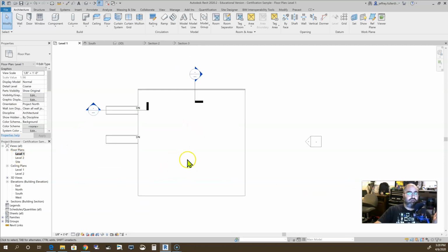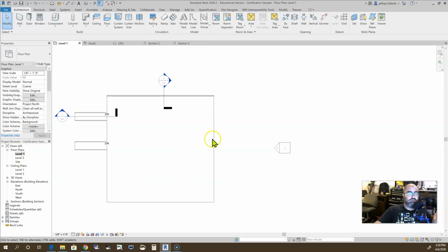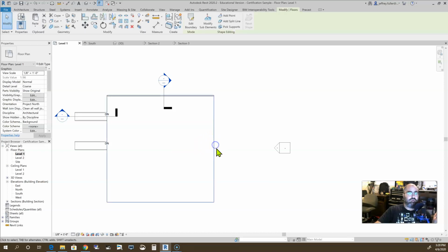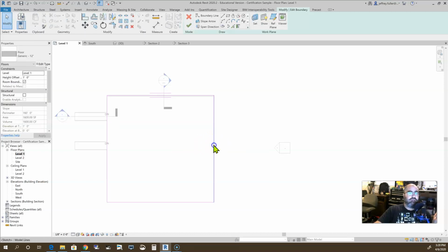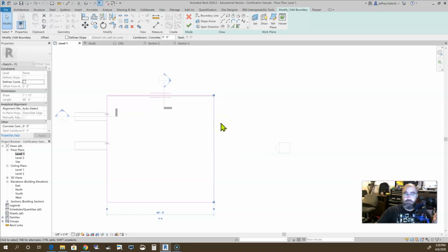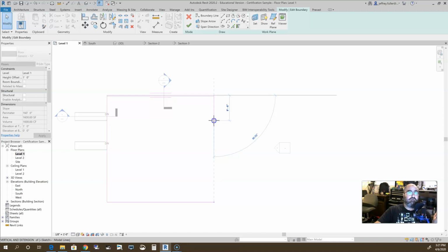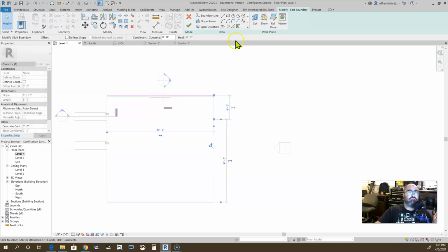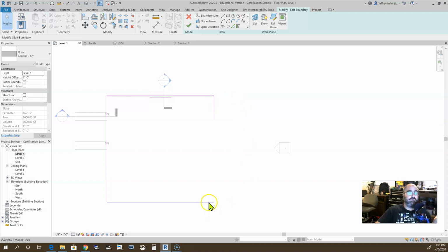Let's create a curve somewhere. Let's say right here on this line. Let's go ahead and double click. I'm going to edit this. Let's see, what I'll do is I'll shorten this line to about 9 feet. Okay, and I'm just going to copy that line and going to mirror it right over here to that side.